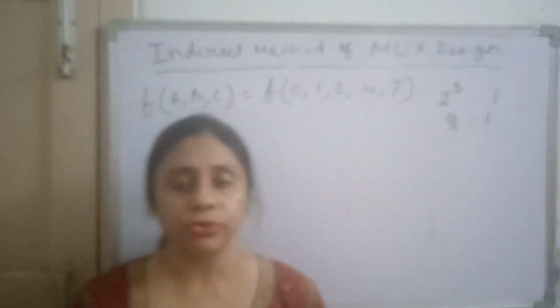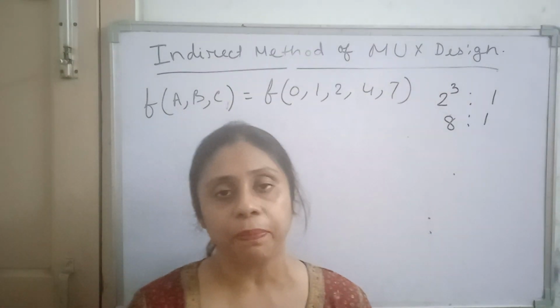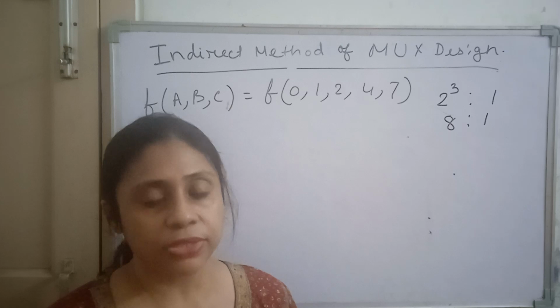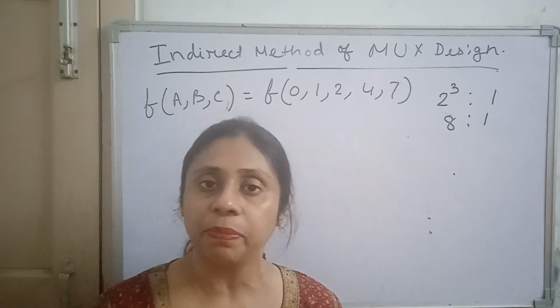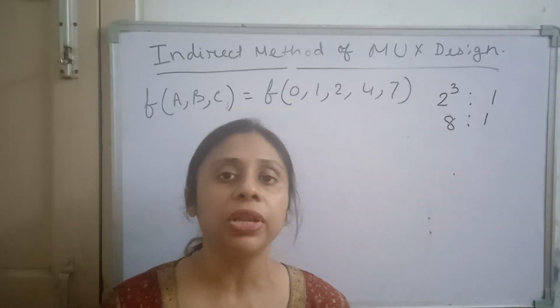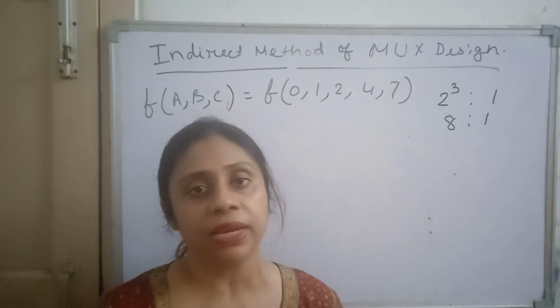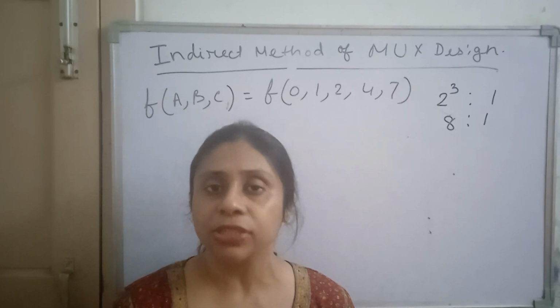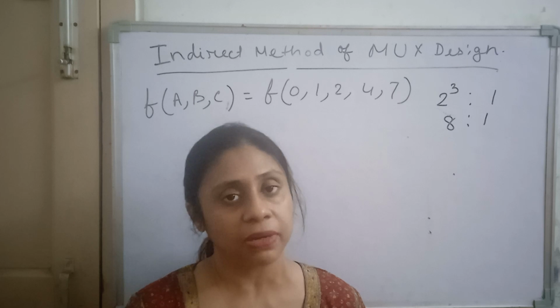Good morning students. Today we will learn how to design a multiplexer in indirect method. So this is indirect method of multiplexer designing. Now what is the utility of designing a multiplexer in indirect method? Actually it is used to halve the size of the multiplexer.